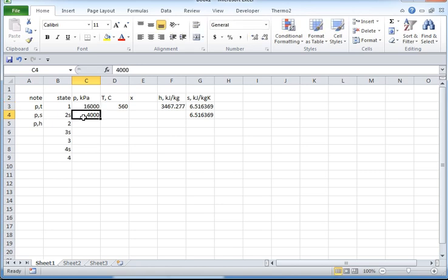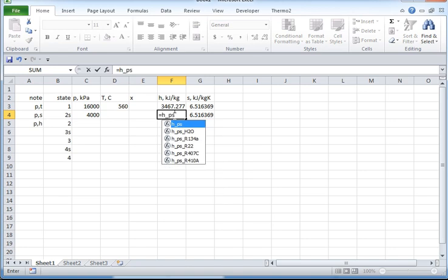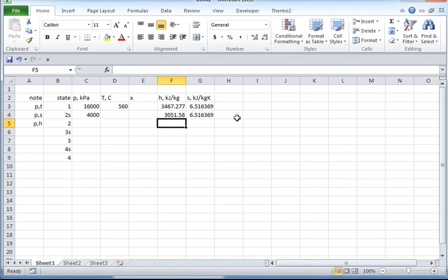See? That's the value of the spreadsheet, 16,000. Now that these two are fixed, we want to get enthalpy as a function of pressure and entropy for H2O. Get the pressure. The entropy is underneath this, and it's hard to do. So I click below it, grab it, and scoot it in. Or just type the cell G4. You'll get frustrated sometimes. It's like, hold it, it's covering up what I want to click. So click on a side cell, grab it, and scoot it in. That's one way to do it.